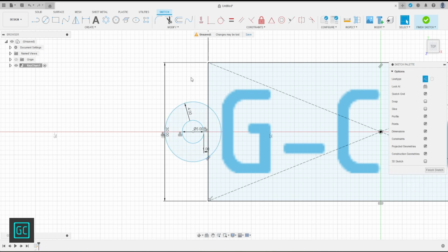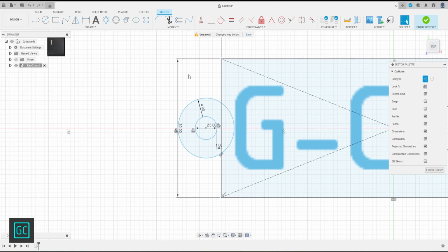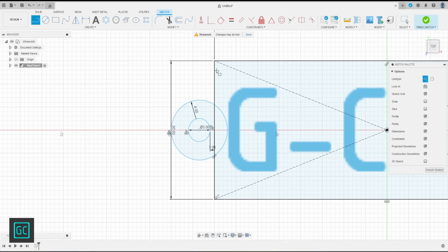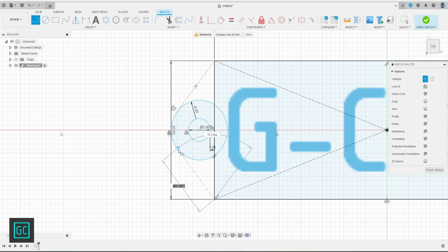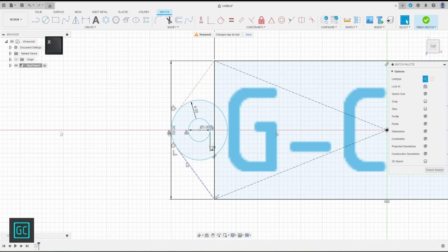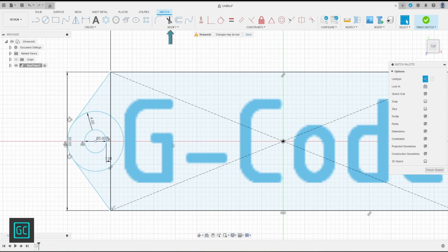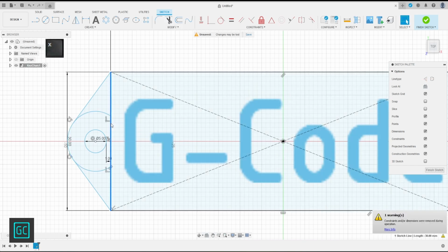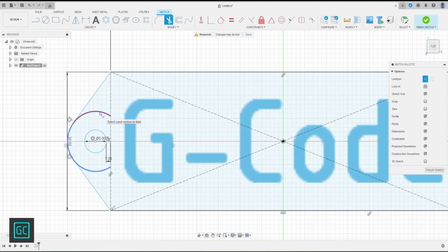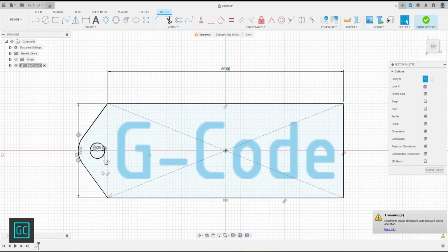On the left top of our rectangle, we're going to press L for line, and then we're going to drag it down to our circle. When we drag it down to our circle, you'll see a round circle. Wait for that indicator and click on it, just like this. And we're going to make these lines solid lines. And we're going to trim our axis circle right there. Going to make this line a construction line. Remove this part and this part of the circle.